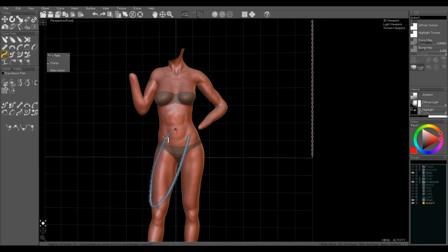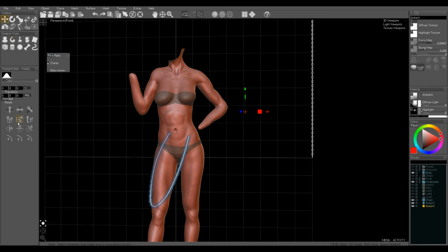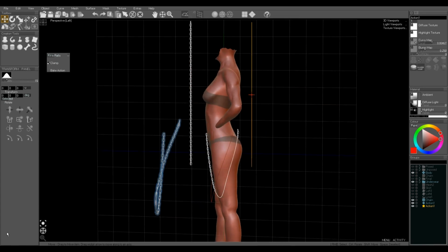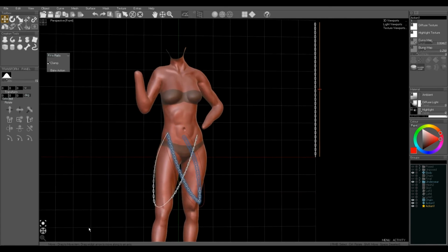And we can use all of the curve tools to smooth out parts of the curve. I've now duplicated that action, and I'm going to mirror it. Unfortunately, the original curve has now moved off the chain, so to make the action work we need to move the original curve back on top of the chain. So just line that up with the original chain again.